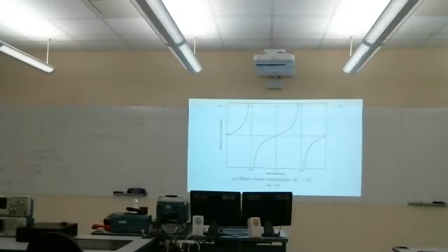So just a length of transmission line can actually replace a physical inductor or capacitor. And so this is often used, again, to do impedance matching, which we'll talk about next time. But this does have application.